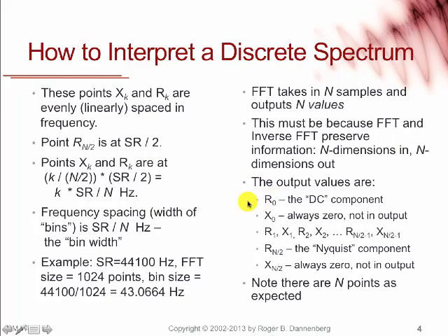So here's how we pack these coefficients. First of all, the first element of the array, in other words, at location 0, is r sub 0, the cosine of 0 component. Cosine of 0 is just 1. It's not actually oscillating, but we're integrating all of the samples. That's the first coefficient. This is sometimes called DC, or direct current component.